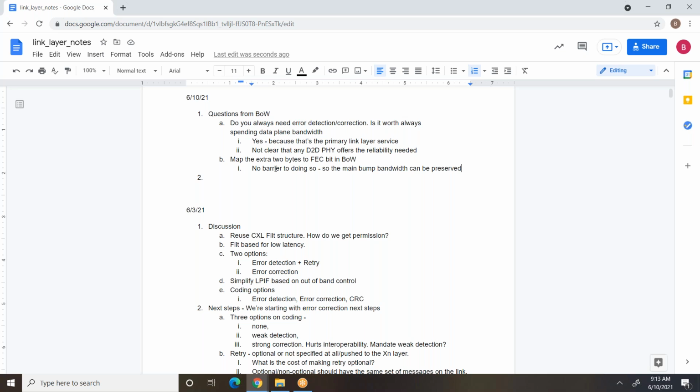So do you then just offer less bandwidth to the transaction layer? Is that how it works? My overall bandwidth is n lanes by, say, 64 bits, right? Okay. And within that bandwidth, I have the data payload plus the FEC, and I just effectively straddle the flit boundary to push in the payload plus the FEC at the end, and it just wraps around after so many flits.